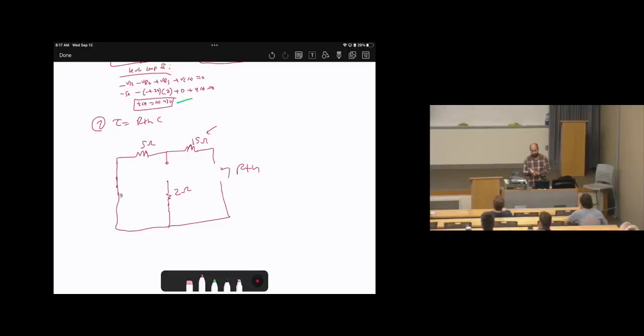That's one of the common mistakes, or the fatal mistakes, that I used to see many students fail on. Some of them say, okay, the 15 ohms resistor has already been cancelled in step number 1, so I'm going to cancel it here. Don't cancel it here. Consider each step as a standalone, or as a different question. They are all independent of each other.